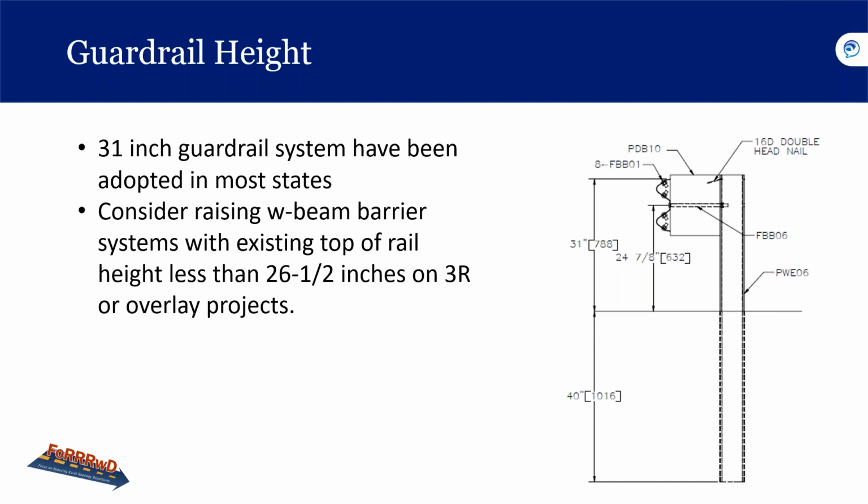The MGS represents the combination of these factors. The MGS has also been crash tested with 8-inch blockouts, and the Texas DOT has been doing it since 2012. They are prepared to submit a request for eligibility. So these studies have been going on all the time, but that's a little bit of background from the early 2000s. Other systems were subsequently developed that also have a 31-inch mounting height.